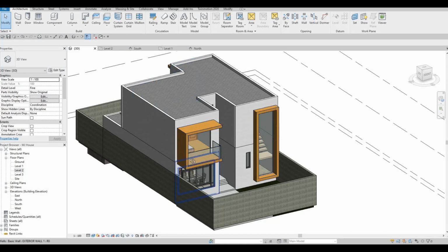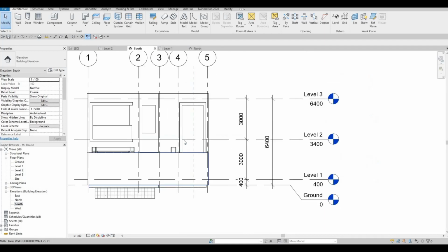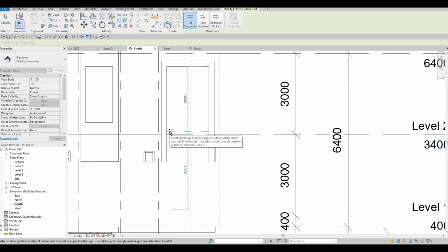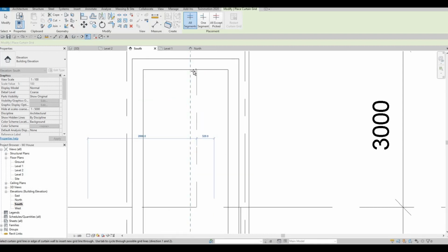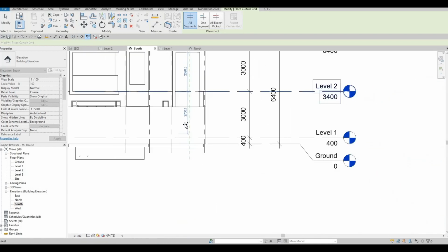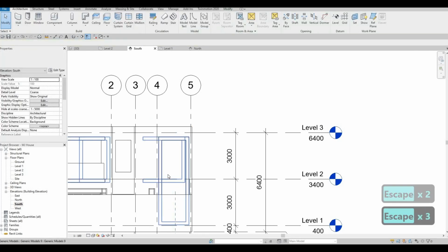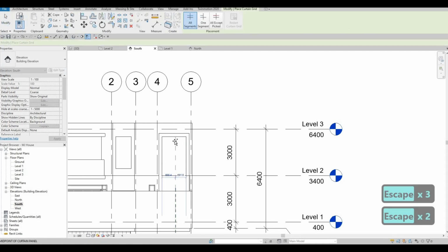What I want to do first is to add the curtain grids so that we know the design that we want on this one. So let's go to south elevation, and I'm gonna create something right here. Go back to architecture, click on curtain grid, and here I just want to do the design. I'm thinking of just putting in something in the middle for the curtain grid at the moment, because we have a reference plane. That reference plane is making it hard for us, but I just put it below, and then now we'll be able to get the midpoint of what we have there.